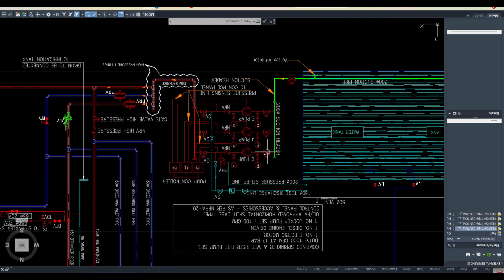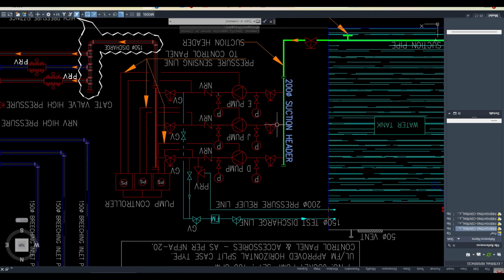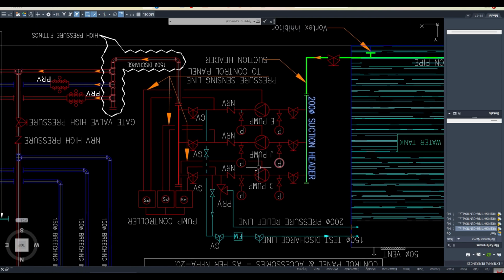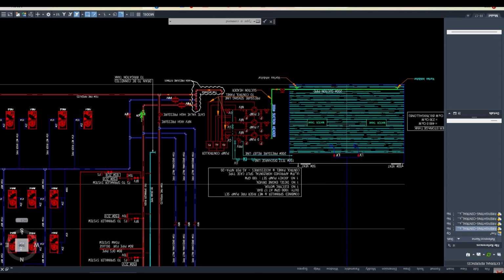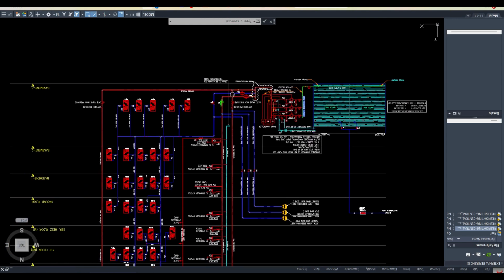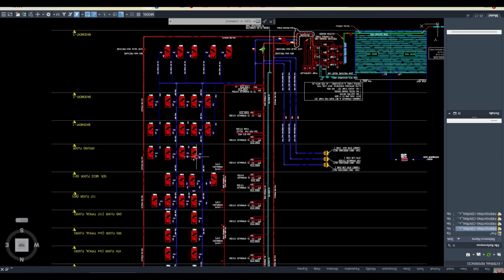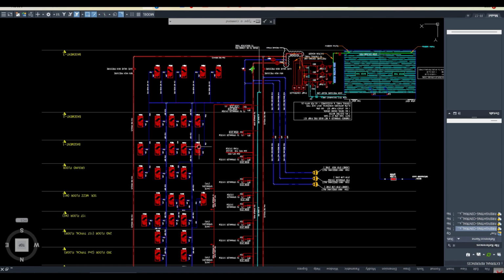And here also, arrangements, I told you that this header should be not less than 1.2 meter from the pump. Okay, the suction header, this header to the pump. So if you know all these things, then you know whether my plant room is enough or not, space wise. Is it too compact, or can I arrange all my services or not. Okay, so anyway, that is covered now. So from here we are covering, this system is connected like this. Now we understood the installation here.